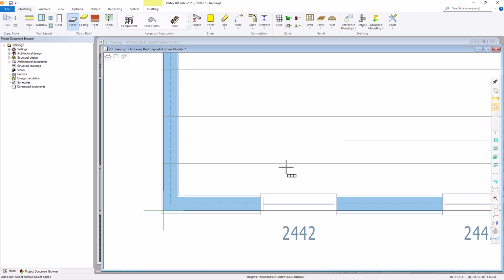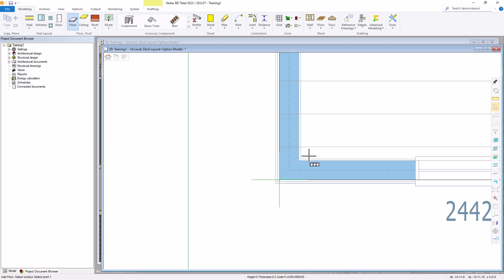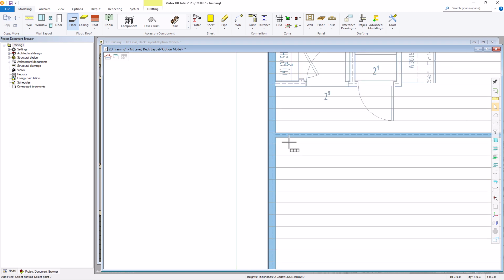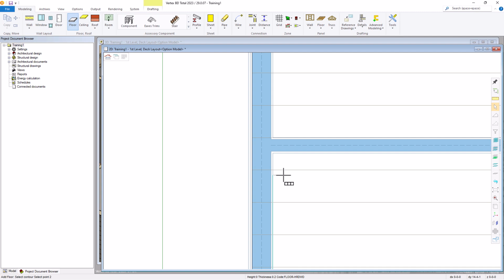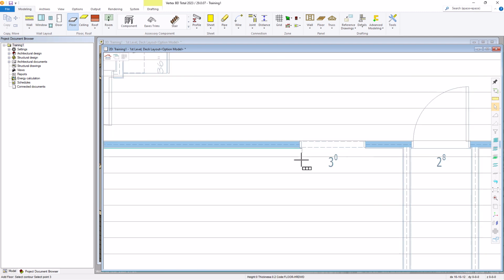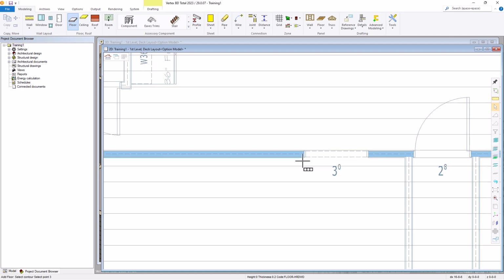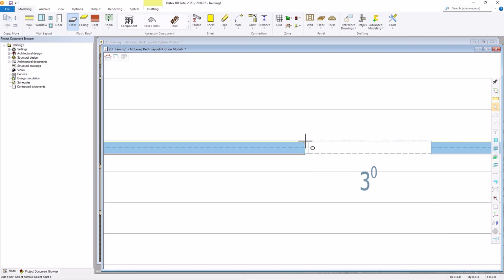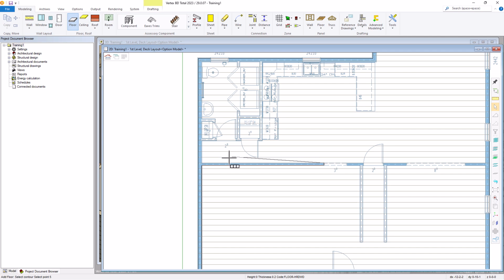So let's start at this lower corner. I'm going to select the drywall or interior finish line for this. Click on that. And I'm going to lock this in the I constraint for the vertical direction or Y axis. And start clicking my points. Going around. Hit U for the X axis. And I'm just going to go to this endpoint and cut across and select the other side of the wall at the finished corner. I'm going to come around.